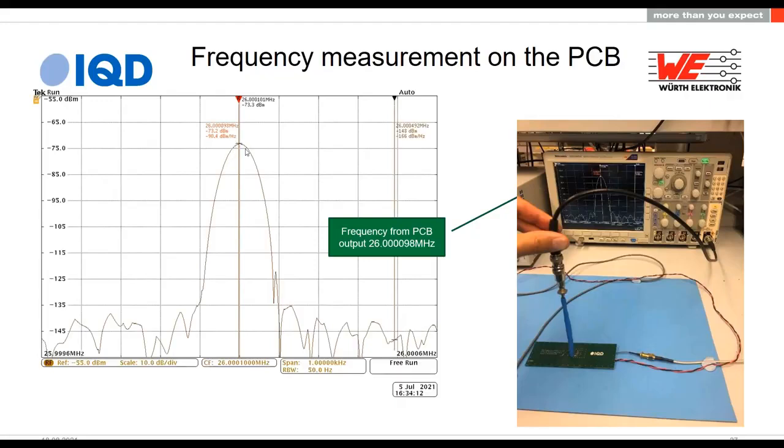It's important to remember here that you need to measure frequency down to a few hertz. Otherwise, you can't resolve it accurately enough for the measurements we're discussing here. So I was able to do that using a spectrum analyzer. The peak here told me to just a few hertz, and that was accurate enough for what I needed to do. Okay.